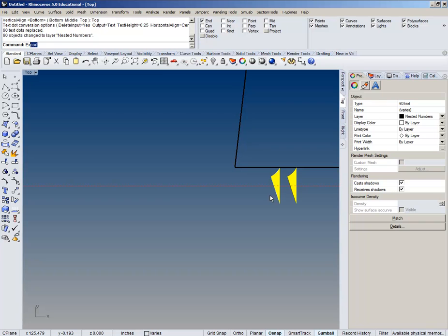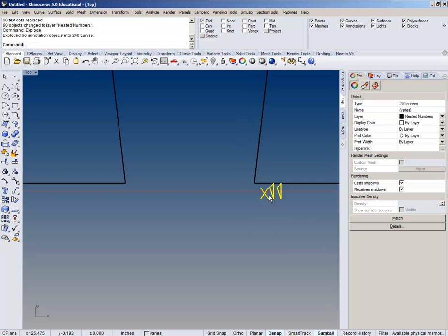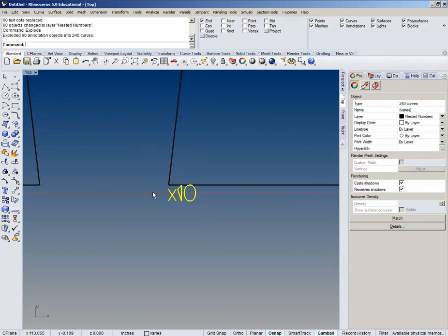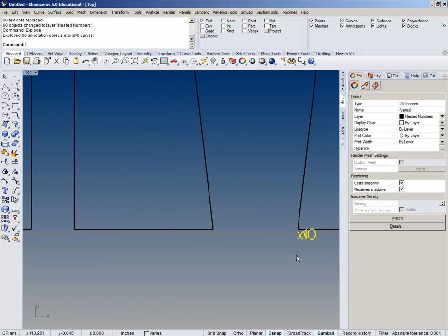Now explode. By default, it gives it a fill. That's why we want to explode it, because if we try to bring this into the laser, it's going to try to etch that solid thing there and make that shape. So that exploded it, and this single stroke basically gives you the outline of it. That font's meant to be exploded to just draw outlines of things.